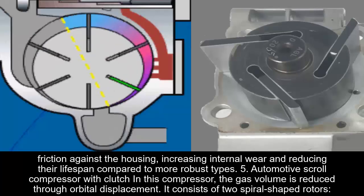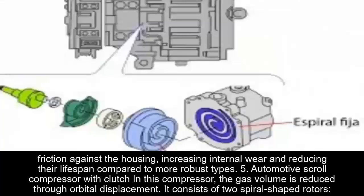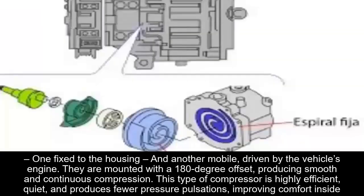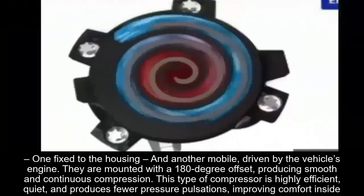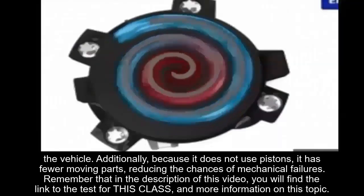5. Automotive scroll compressor with clutch. In this compressor, the gas volume is reduced through orbital displacement. It consists of two spiral-shaped rotors, one fixed to the housing and another mobile, driven by the vehicle's engine. They're mounted with 180 degrees offset, producing smooth and continuous compression. This type of compressor is highly efficient, quiet, and produces fewer pressure pulsations, improving comfort inside the vehicle. Additionally, because it does not use pistons, it has fewer moving parts, reducing the chances of mechanical failures.